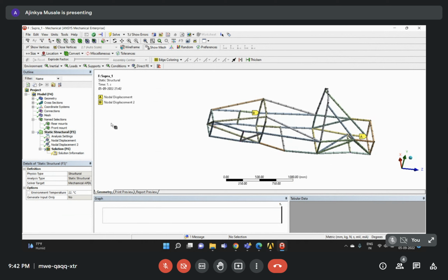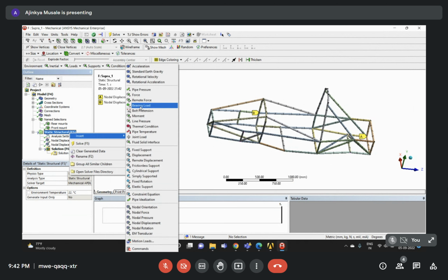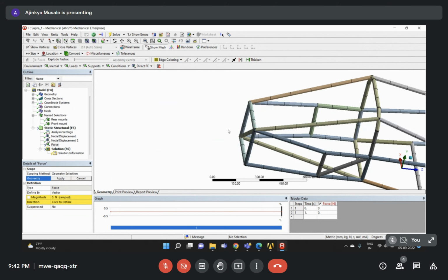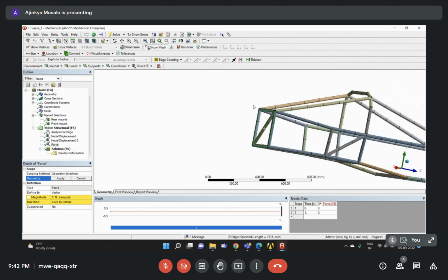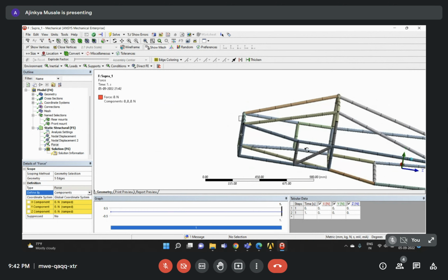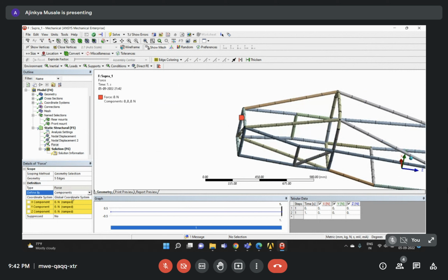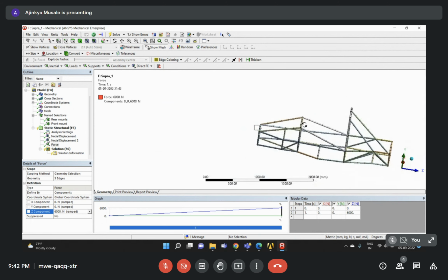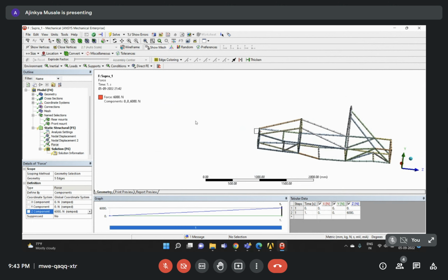Okay, now I have the collision from the front side. How can I define that? I can simply define a force, and define that force on the members. Maybe I can select one, hit Control, 2, 3, 4, and even this one. So all these members, I'm applying a load. You can see I will apply it by using components. Let's check, Z will be the direction, and it will be 6 kilonewton. Can you see the load? Which is nothing but my front collision, right?